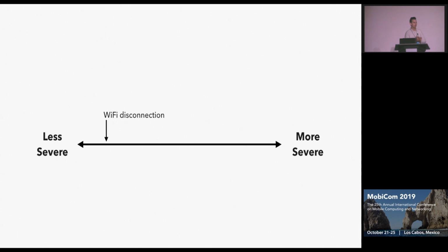A less severe problem would be Wi-Fi is just not working. It's disconnected momentarily. That's not a big issue because our sensors are designed to handle that. They'll still collect data while they're offline, and then when they come back online, they'll reconnect and upload the data. But on the other end, there's something like maybe a bug in the code, or a hardware malfunction, or probably the worst case, no power. It's either purposefully or accidentally unplugged from power. That happens all the time in homes.